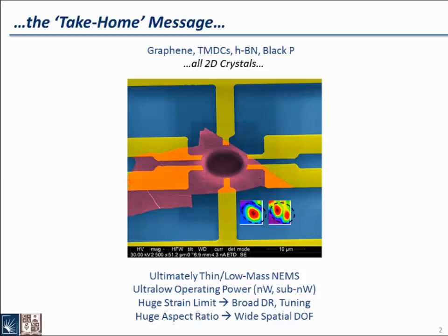And then we have also transferred atomic layer semiconductors onto this substrate, and you can see they're connected. So you can immediately see there are multiple transistors here because we are talking about semiconductor crystal now with source and drain electrodes. And then we also have a backgate underneath the silicon oxide. So that makes a number of transistor devices. And then this circle part is hollow because there's a cavity there. So it could be an optical device and also a mechanical device.